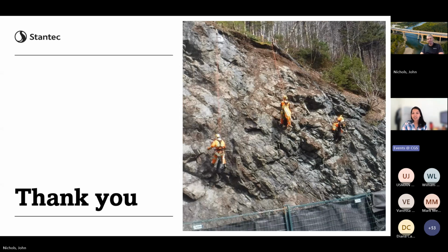Okay, one last one to end our session. You mentioned the use of split spoon during exploration. Can split spoon be used during rock exploration? I think when I said that, I was referring to an oriented core: if you do an angled borehole, you can't do a split spoon because it doesn't really work. But I would typically not. Split spoon is a soil parameter.